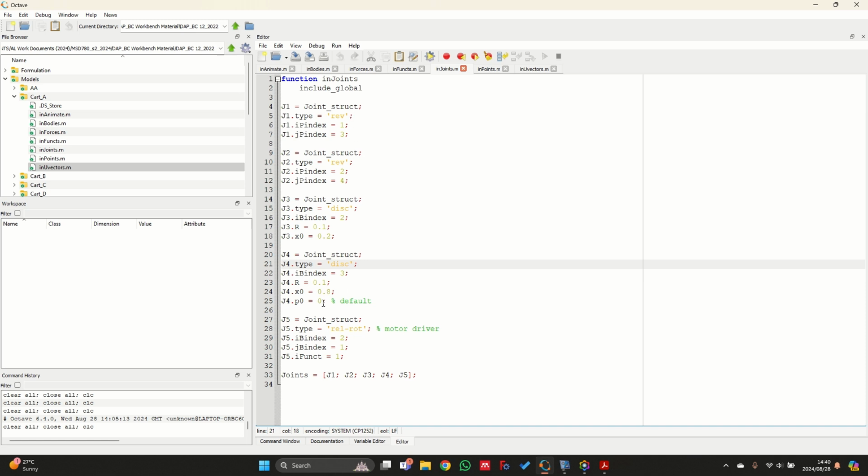Once these 4 joints are now specified, then I can specify my relative rotation driver as well. And this is similar to what we did for the pendulum rod. In this case, we specify the type as REL-ROT, so that's the relative rotation driver. Then we have an I body index and a J body index. And you'll remember from our calculations that we said body I is body 2 in our case, and body J is body 1. So I just denoted it in this form. And then I just have to give the actual driver function as a final input. In this case, it's equal to 1.